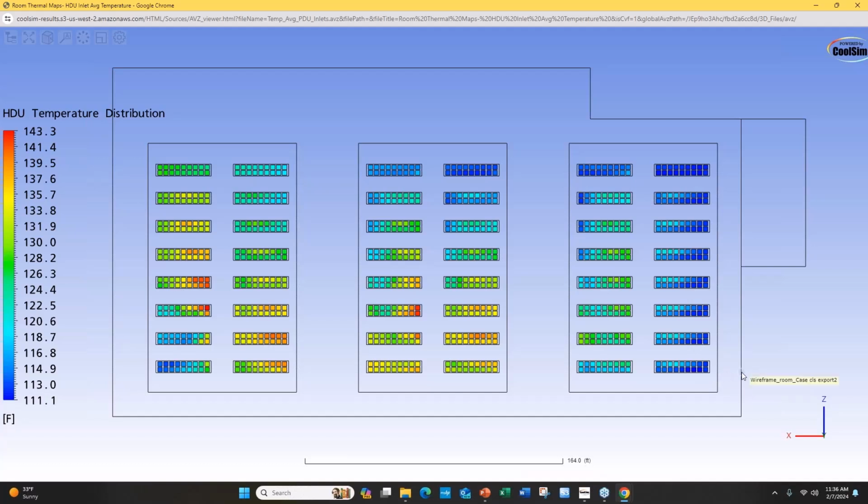Again, you look for the corners of your design, what we call the four corners. In this case, high temperature, worst wind condition is what you want to model to understand what your aggregate cooling capacity will be on a given day. You can calculate it by understanding what that average temperature inlet is, and then determining what the efficiency of this heat exchanger is with an inlet temperature of 143 degrees. Or conversely, how hard your chiller's got to work to lift the pressure in the compressor high enough so that the cooling medium is well above 143 degrees.